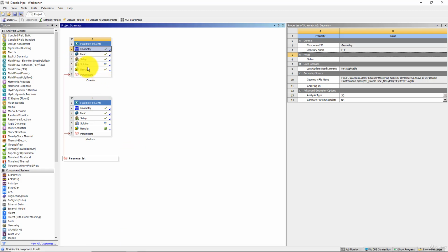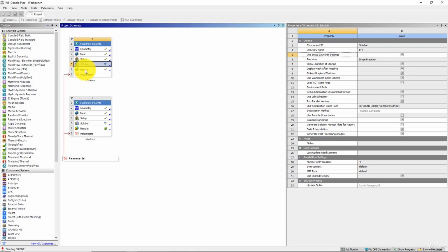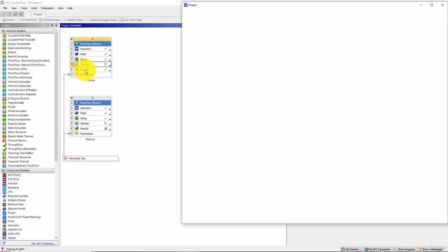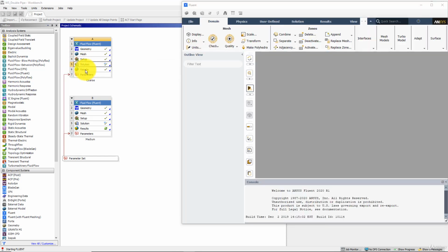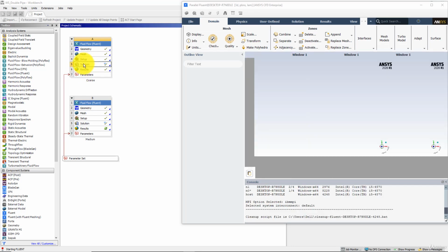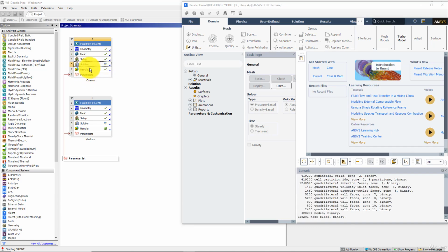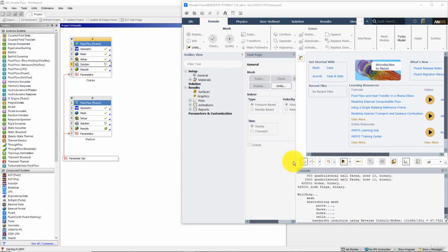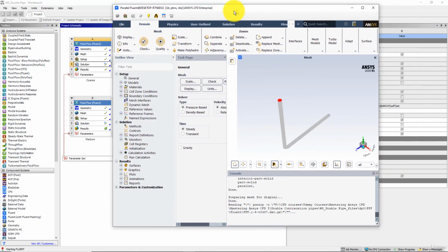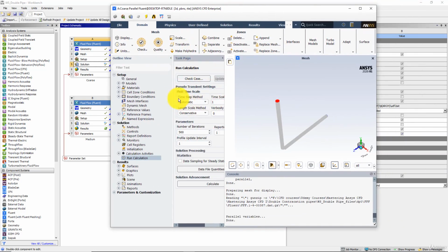And now I'm going to open the result file from this fluid flow for the coarse mesh from solutions. This is the cell number A6. When you double click on here, this will open results file of Fluent in CFD post, and this is the topic of the next section on the post processing of results in CFD post. Right now we are doing everything inside the Fluent's own capability for post processing.